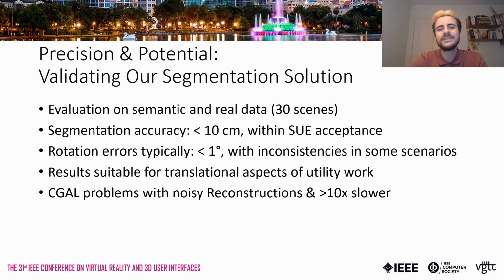We evaluated the segmentation on a dataset of 30 real-world excavation reconstructions. The fitting approach was further evaluated on synthetic data. The evaluation shows an accuracy of less than 10 centimeters for the proposed segmentation approach, which is within SUE constraints of about 20 centimeters. Rotation errors remain mostly smaller than 1 degree, but contains inconsistencies in a few cases.